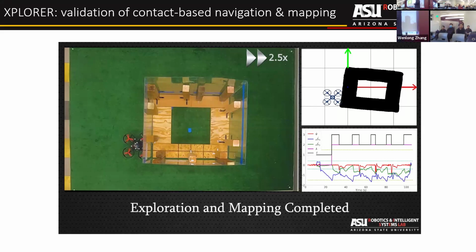Is the drone always trying to go to the left? Why would you go like that at the edge? The reason is because, for example, if you continue going like this in this particular direction, the wrench estimate will change. Here, the wrench estimation is in that direction. But when it goes to here, let's say one propeller is here, the other one is not, then the wrench estimation will be in that direction. It will turn, right?